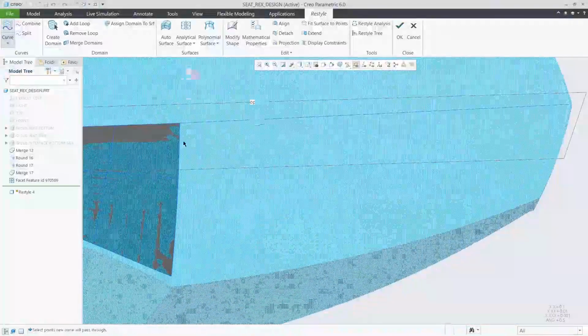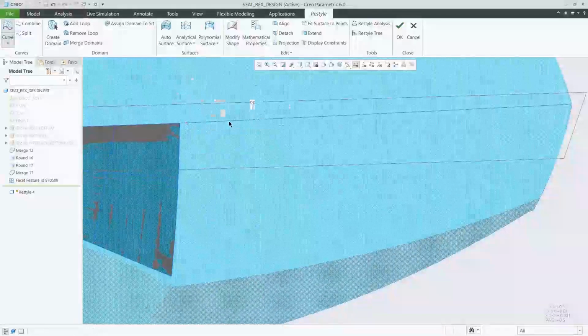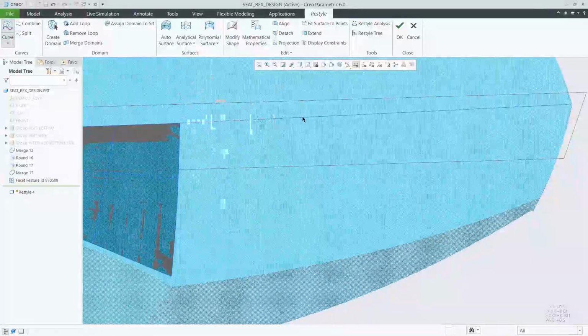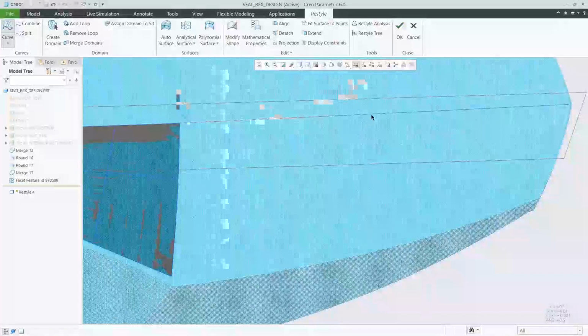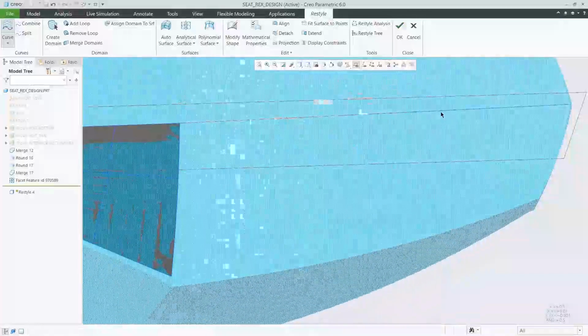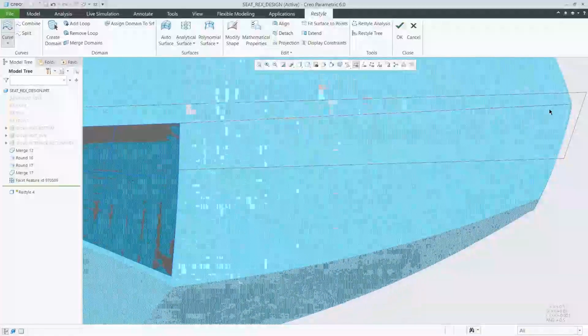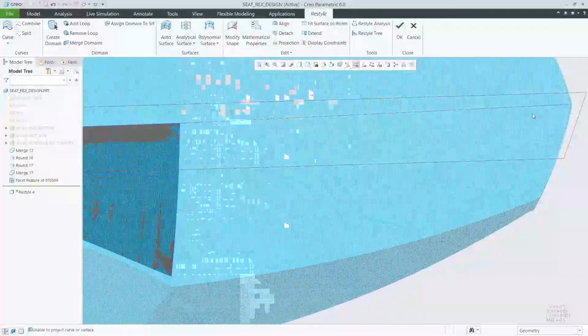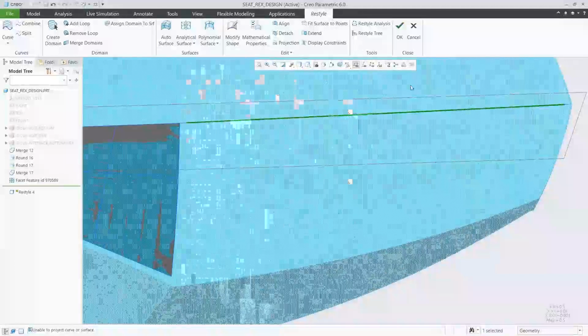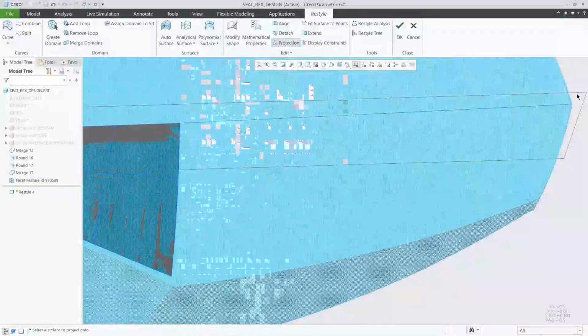And just like we did on the first surface, I'm going to start by moving along the first section curve that we have going down the middle of our part, or our scan data, just simply laying out some points that are going to follow along that path that we want to go. And once we have that, we can again project that back onto the center plane just to make sure that we're aligned well there.